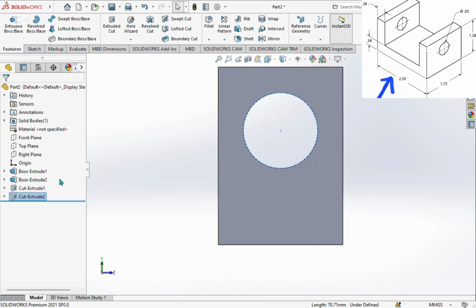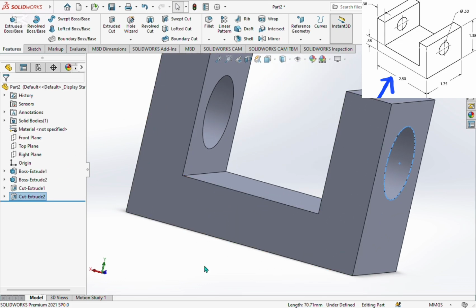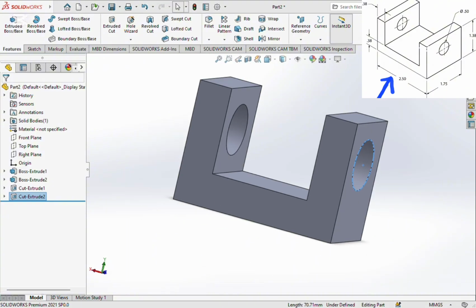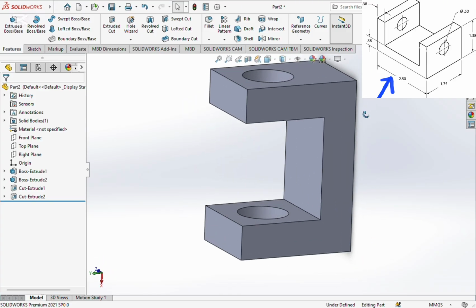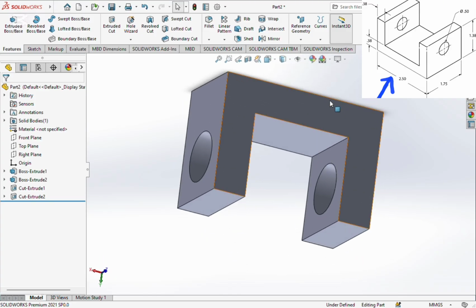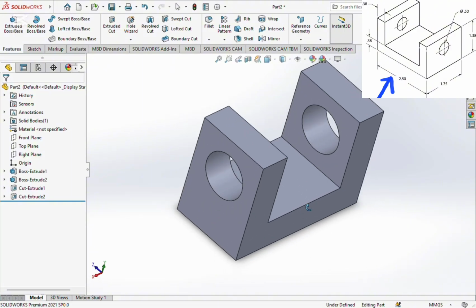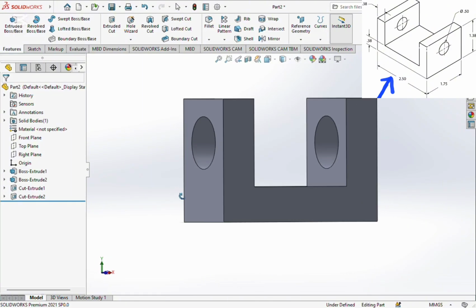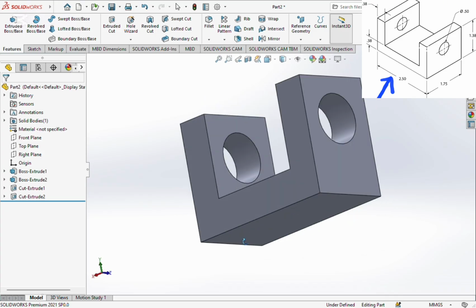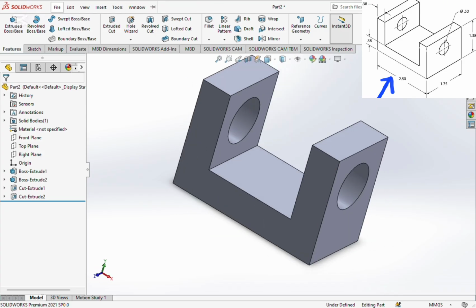So when I extrude the cuts, 20 is already there, then I enter. Automatically on its own, it enters. Now I use my mouse to pan it. I've told you how to pan. Use the scroll wheel. Instead of scrolling it, just press it down, then move your mouse left and right, up and down, like that. You can pan. Now the next part, I want to get it in auto.